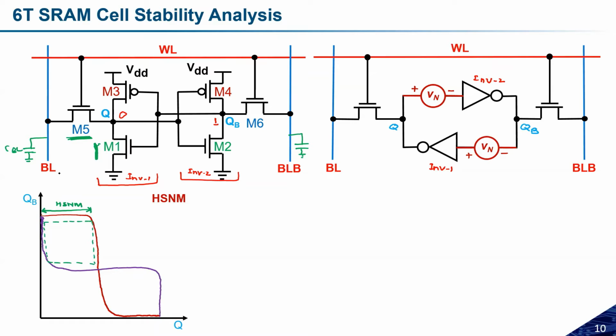Okay, so if I want to perform the read operation, in the last lecture I already discussed how we can perform it. For read operation, BL is 1 and BLB is 1, both are one, and both bitline capacitors should be charged. Let us assume CBL and CBLB. Both capacitors will be charged, and now I have to connect one sense amplifier between bit line and bit line bar.